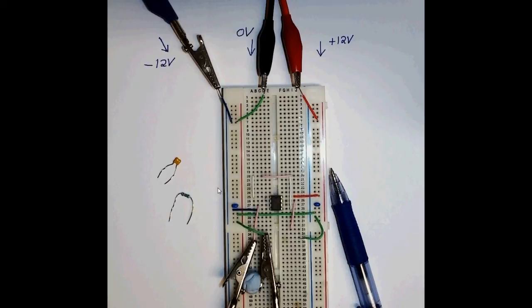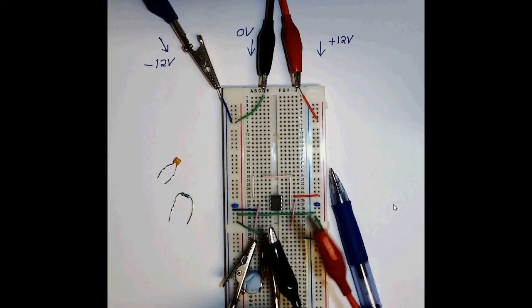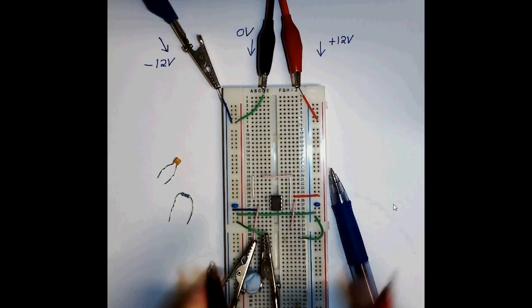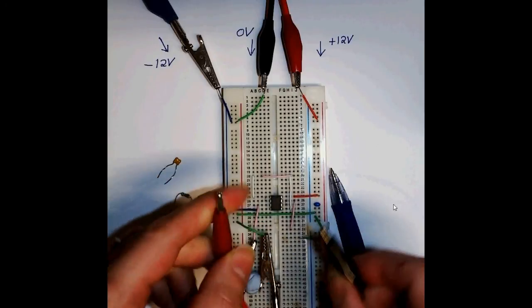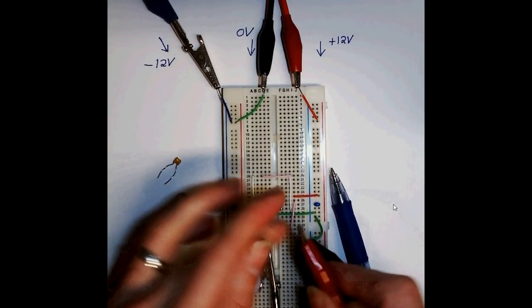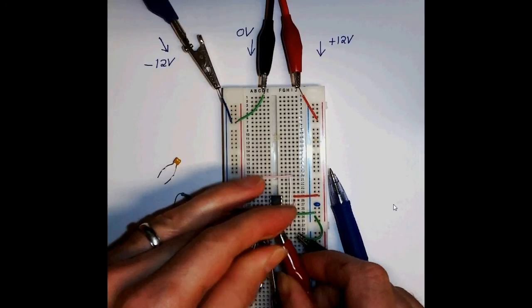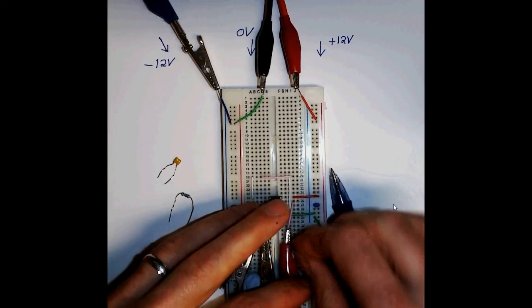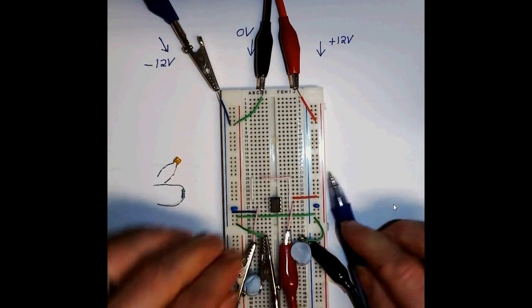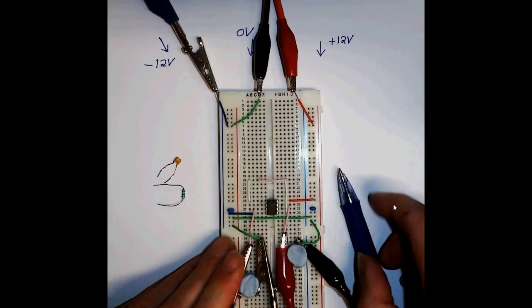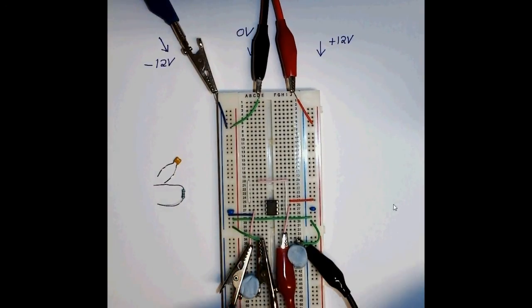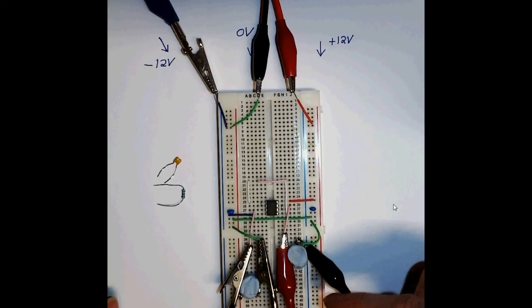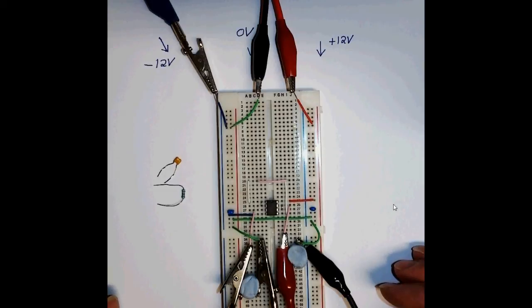There, that's better. On the output side, I've actually found a rather more friendly set of wires. I can just connect the shield, the black one, to the ground of my circuit, and the signal itself to the output there. And again, just to stop them touching, a bit of blue tack to keep them apart. Fine. Plug the other end of this cable into the VAM's input port on its sound card section, and that's it, we're ready to go.